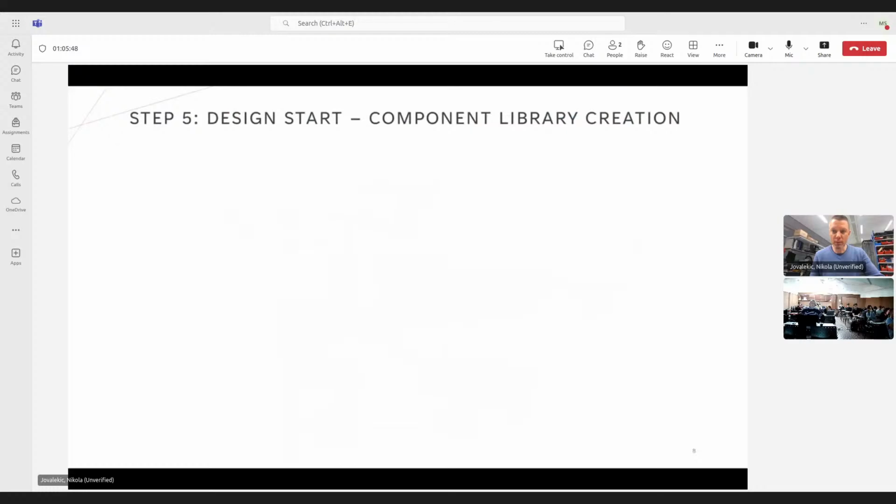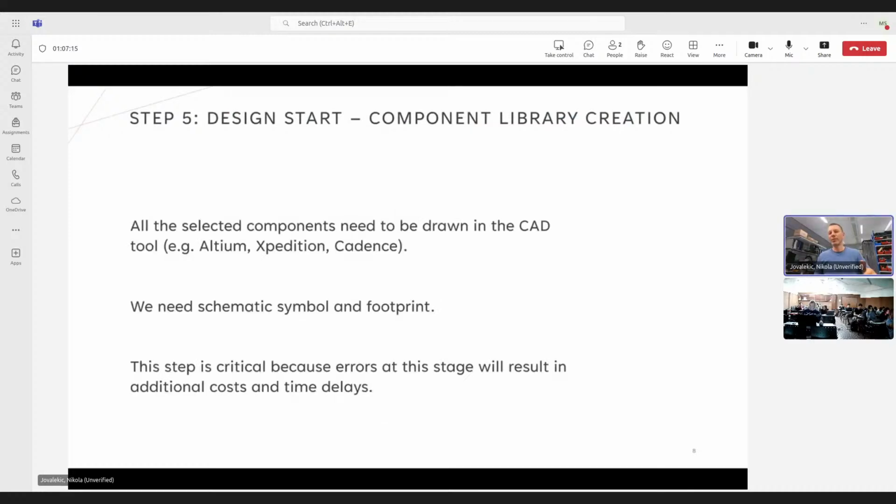Of course, not in all cases, because sometimes it is possible to do some rework, some patching on a PCB so that you can put the component there. But if we are talking about high-speed components like this oscillator, which is at 100 megs, it's not doable, because you will most probably make a big problem. You will radiate everywhere, and you will most probably make the PCB useless, because you will destroy the analog front end, and you will not be able to test at least the analog part.